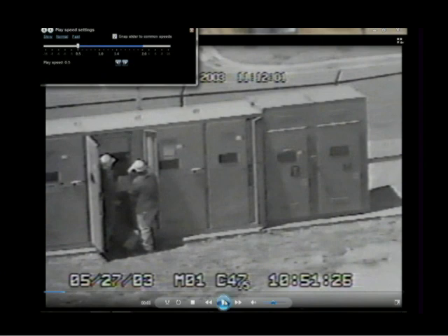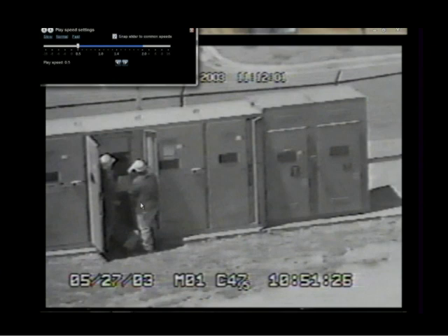Now there's three, let me just kind of set the stage. There's one guy that's inside the enclosure, one guy standing here, another guy standing on the outside. This guy here, I'm about 150 pounds. This guy looks like he's bigger and stronger than me. He has to be probably 200 pounds. Watch about the arc blast, not the arc flash, that's the light, the arc blast. What happens to this guy physically?